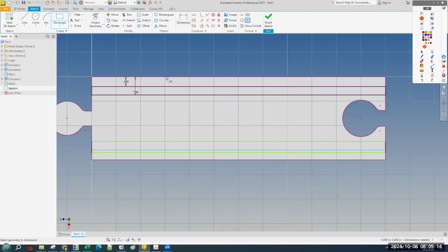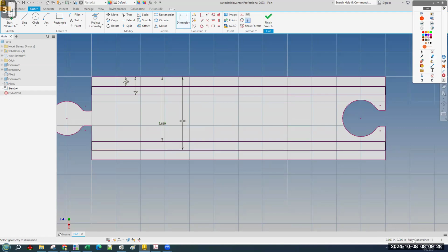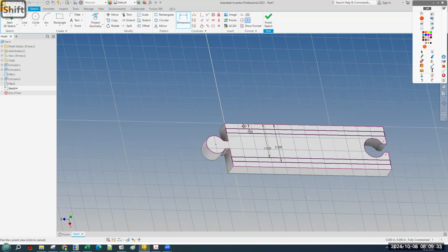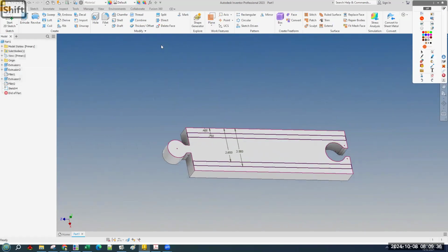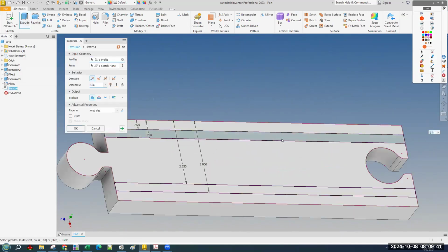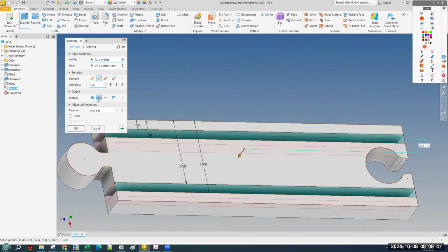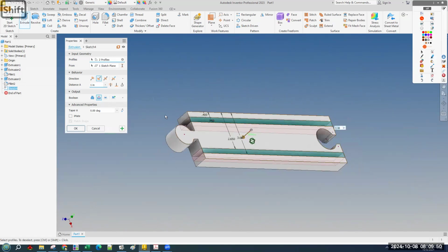So we've got the dimension tool, distance from our first side again to here was 2 point, well, it's a close guess. And from here to here is 3. And there we go. Should say fully constrained down in the bottom corner. And there we go. There's our sketch. Finish sketch. Extrude, looking at it from a side, and choose just the rectangle that you made, just the other rectangle, and switch it to cut. And we don't want to cut 1 inch. We want to cut 0.25.